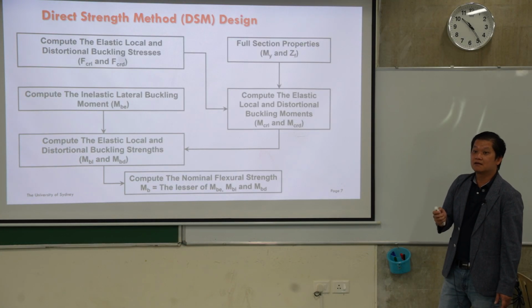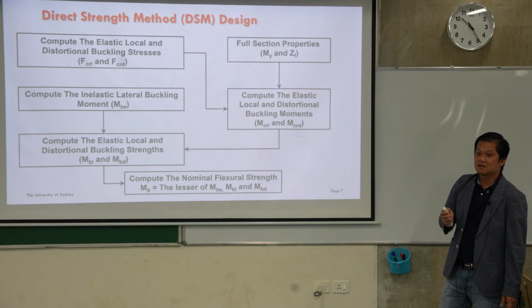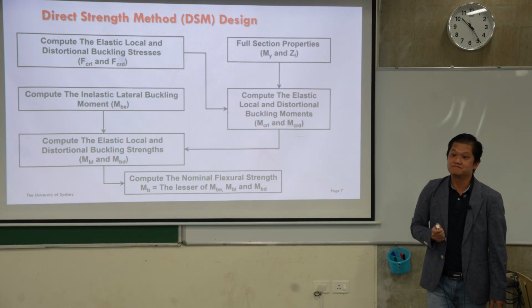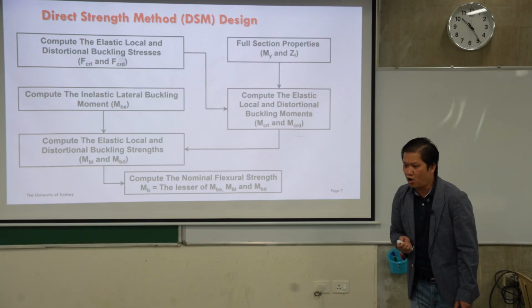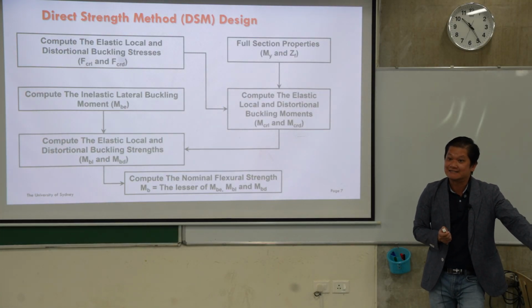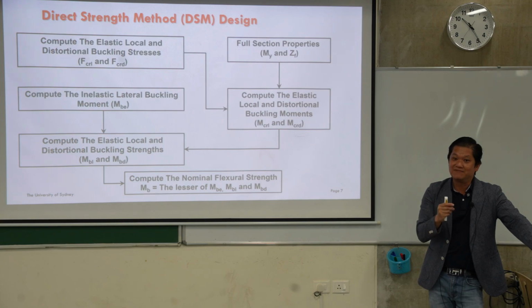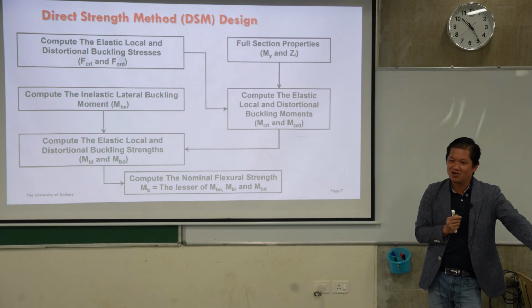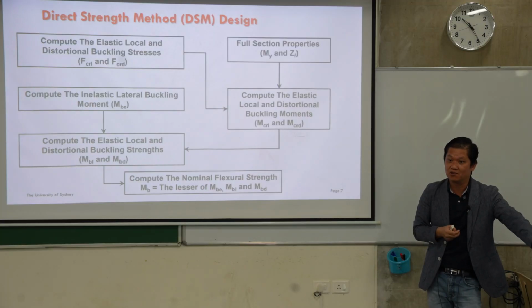It depends on the plate buckling unit. The aspect ratio is approximately equal to the buckling unit, almost local buckling, I can say, almost with the plain section. But when you put a stiffener in, it may be a little bit longer because it's stronger in terms of local buckling stiffness.